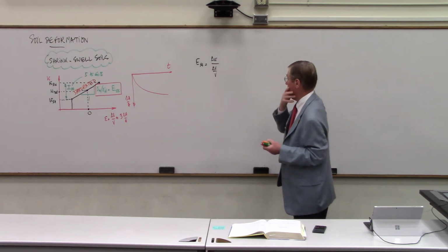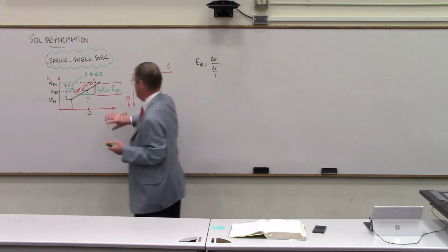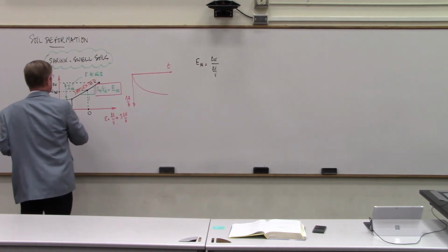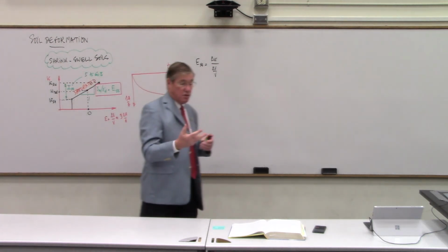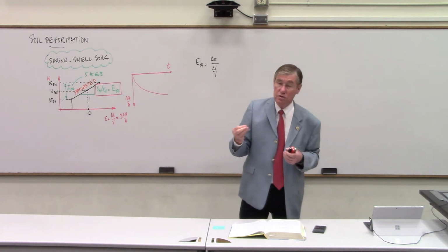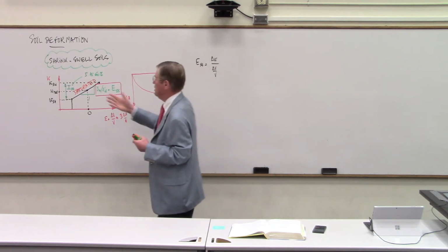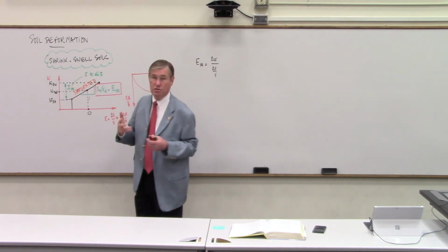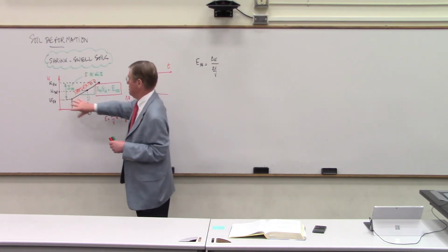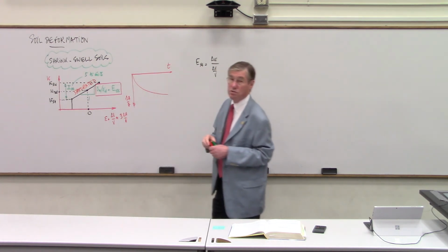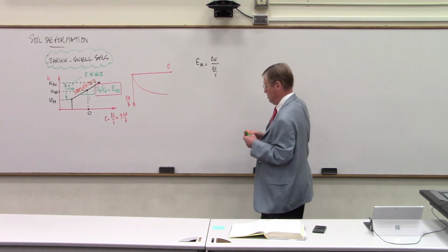That's the slope. And in a way, this is a strain, and you can sense that the water content impacts the suction, and the suction is the water stress, and the water stress impacts the effective stress. So you can look at this, if you wish, as if it was something equivalent to a stress strain curve. And so that's why we call it the modulus here, because this, in essence, can be thought of as a stress strain curve model for the shrinking and swelling process.